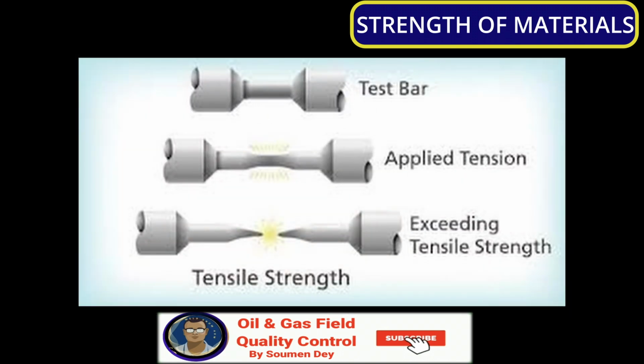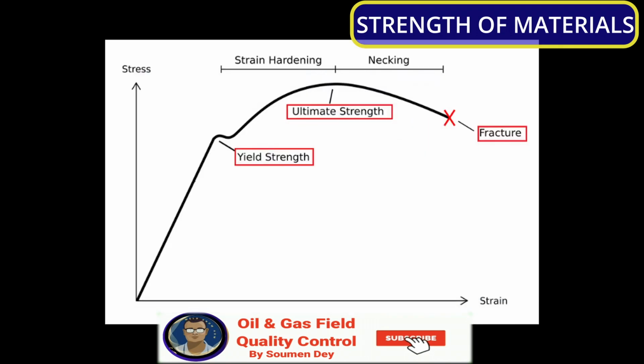Tensile strength is defined as the maximum load in tension a material withstands before fracturing, or the ability of a material to resist being pulled apart by opposing forces. Also known as ultimate strength, it is the maximum strength developed by a material in a tension test. The tension test is the method of determining the behavior of a material under actual stretch loading. The test provides the elastic limit, elongation, yield point, yield strength, tensile strength, and the reduction in area.